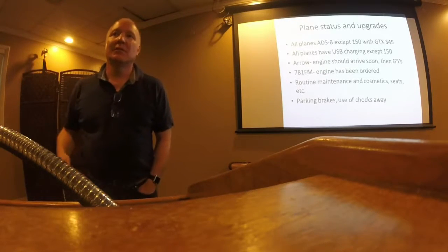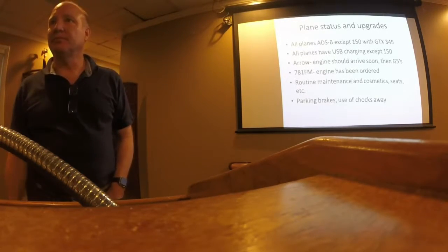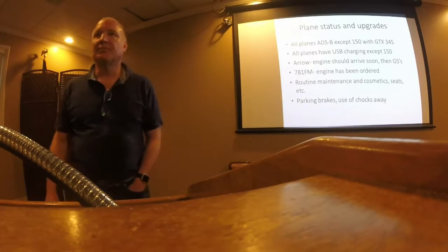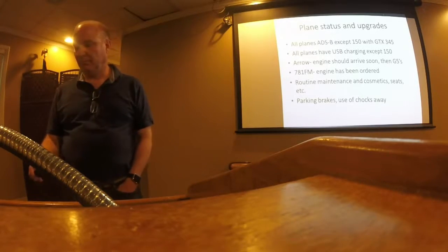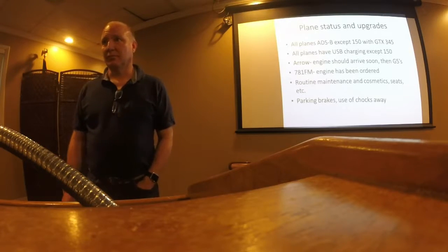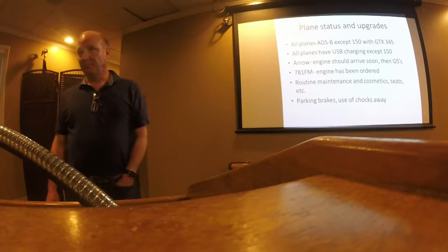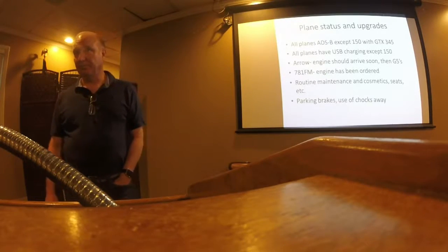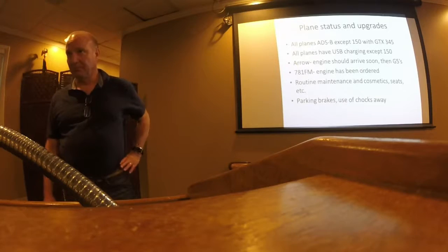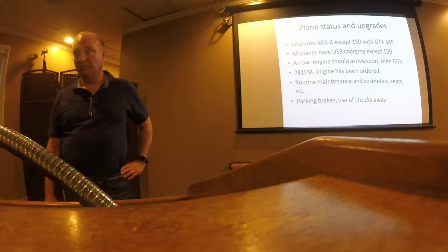The reason Mike Grady was so big on not using the parking brake unless you really needed to is very simple. Parking brakes in a car use a mechanical link to pull the parking brake on with a cable. Parking brakes in the airplane are effectively the same thing as standing there on the brakes the whole time. They keep constant pressure on the full brake system, and in the long run that's not good. That's why you chock the plane and then kick the parking brake off. Yeah, on the Arrow, the brakes actually get mushy.